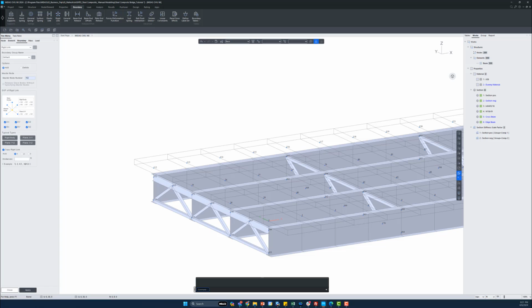Before that, as mentioned before, we'll be doing this for all the places where the cross frames are located. So we know that they are 4 feet. We'll be creating 4 rigid links at 20, then 2 at 10, and lastly 4 at 20.